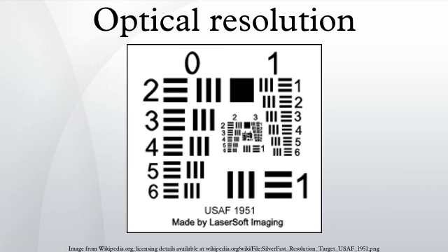A common problem among non-technicians is the use of the number of pixels on the detector to describe the resolution. If all sensors were the same size, this would be acceptable. Since they are not, the use of the number of pixels can be misleading. For example, a 2 megapixel camera of 20 micrometer square pixels will have worse resolution than a 1 megapixel camera with 8 micrometer pixels, all else being equal.